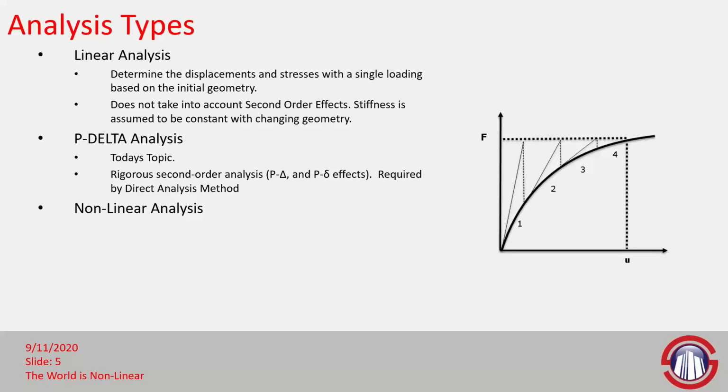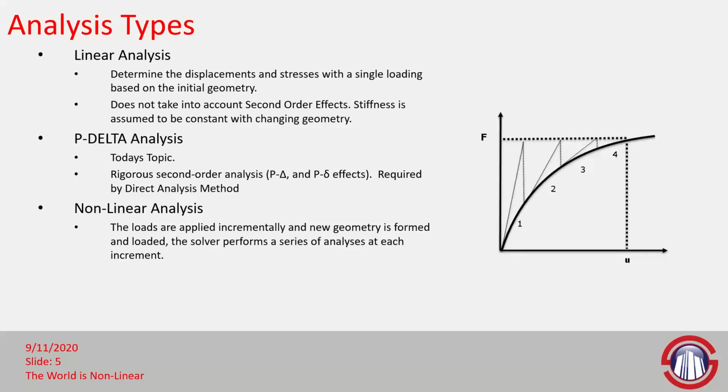Then we have nonlinear analysis. And we'll talk about this as well today. Basically, how this works is the loads are applied incrementally and new geometry is formed and loaded, and then the solver will then perform a series of these analyses with each incremental addition of the loads.